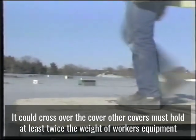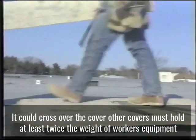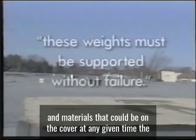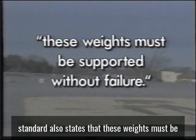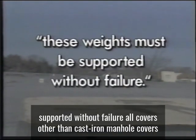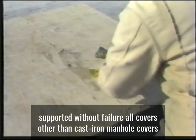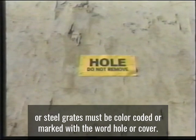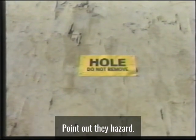Other covers must hold at least twice the weight of workers, equipment, and materials that could be on the cover at any given time. The standard also states that these weights must be supported without failure. All covers other than cast iron manhole covers or steel grates must be color-coded or marked with the word "hole" or "cover" to point out the hazard.